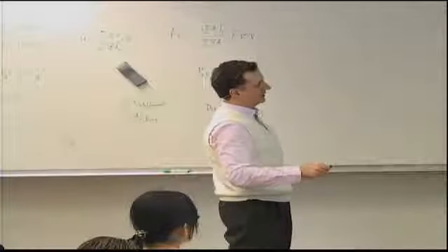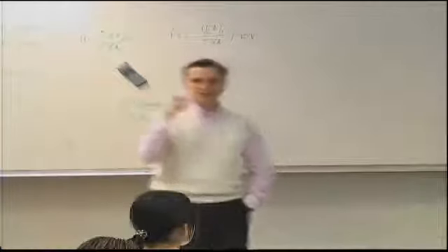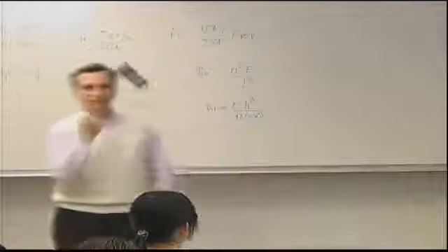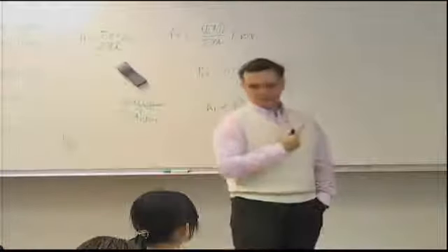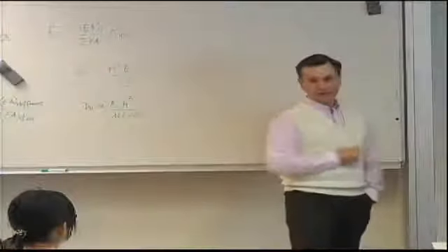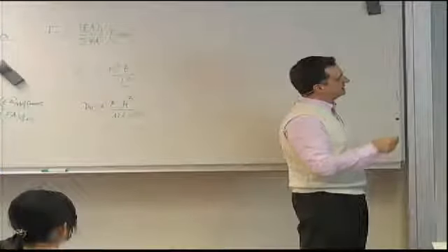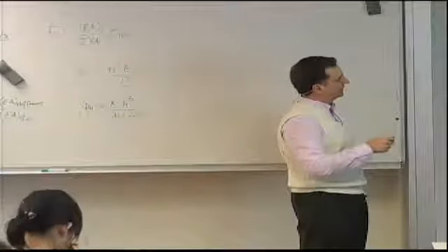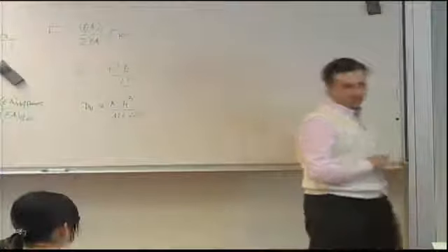Basically, if you had protruding head and you were out here, you would get about 20 millimeters. That means if you had more spacing, you would actually have inter-rivet buckling. And that's a problem. That's a major problem. The spacing that this flange requires to avoid inter-rivet buckling turns out to be less than 20 millimeters, would have to be in this vertical region lower than 20 millimeters for any typical B over T used in practice. Now, why would that be a problem?